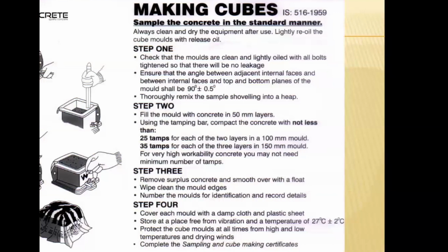To check the quality of concrete, the most important, fundamental and decisive test, we can say, is the compressive strength. Most of the ready-mix producers and most of the clients take this as the one final test for ascertaining the quality of concrete. And we can say this is the most neglected portion of quality control post production of concrete, actually. So many times what happens is somebody comes, just fills up and goes, and your concrete is judged based on some random way of filling up the concrete.